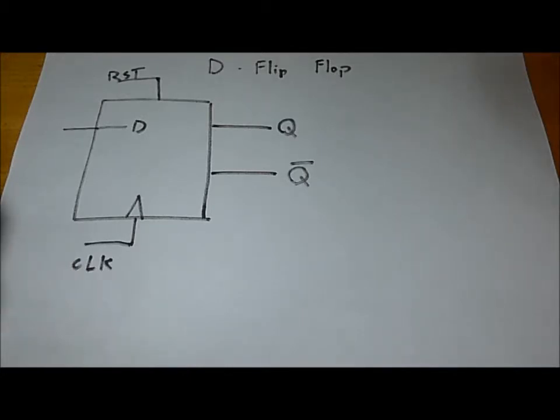A clock signal is merely an oscillating pulse between 1 and 0 that happens at a regular frequency, such as 10 Hertz, 100 Hertz, or 100 megahertz, or 2 or 3 gigahertz. You might recognize these terms from things such as your phone or computer processor. Computer processors usually run around 2 gigahertz. This means that their clock signal is right around 2 billion pulses per second. That's very fast, and that means that their state machines are able to work at that speed.